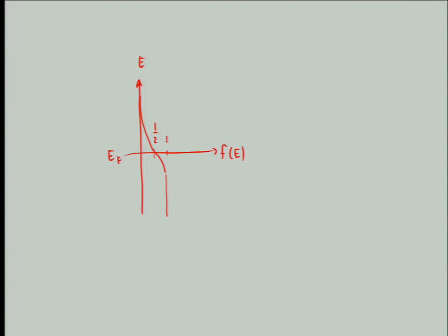Okay. Just to remind you, this Fermi distribution does hold for occupancy of allowed energy states in the metal. Basically, energy levels slightly below the Fermi level have some reasonable chance of being empty, because the electrons from those energy states had enough thermal energy to go up to higher energy. So bottom line, there's a reasonable probability of finding electrons within just a few kT of the Fermi level in the metal. Does that make sense?